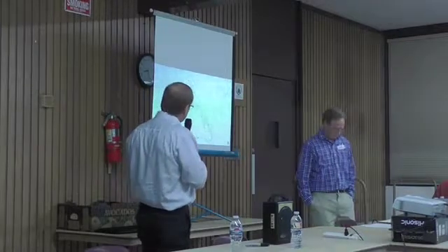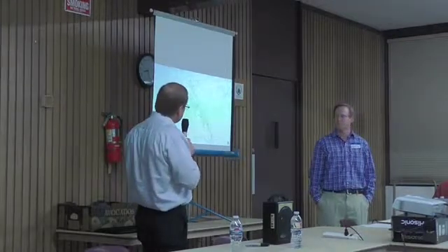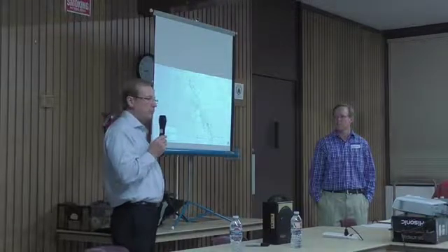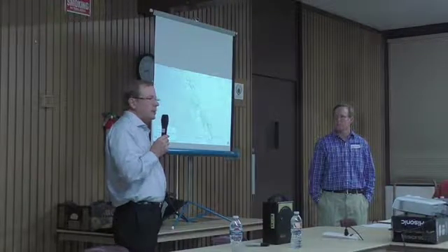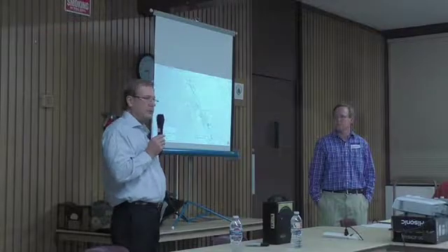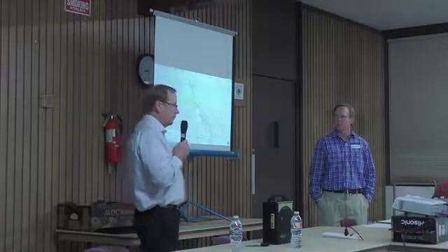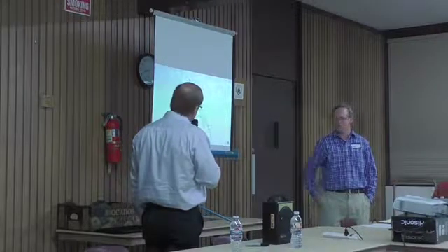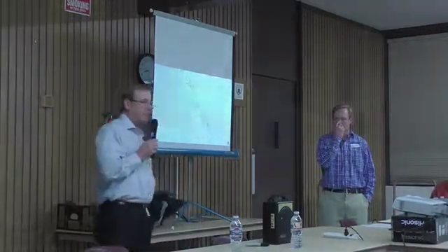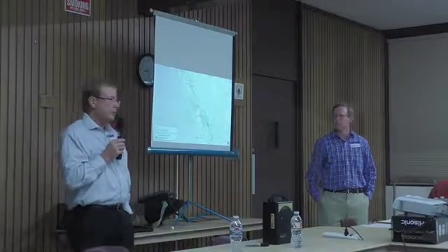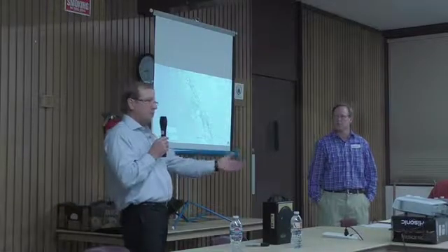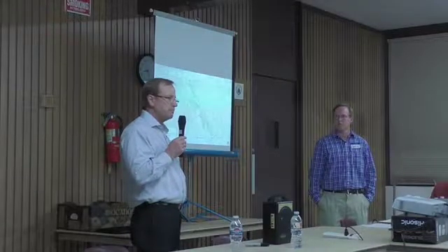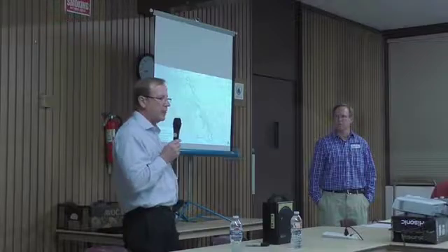As a result of the aquifer system being shallow, a lot of your wells are drawing from probably the upper 100 feet at most of the underlying soils here. And in some places, and it really is variable, the water quality can range from good to having quite a substantial mineral content, typically iron or manganese.